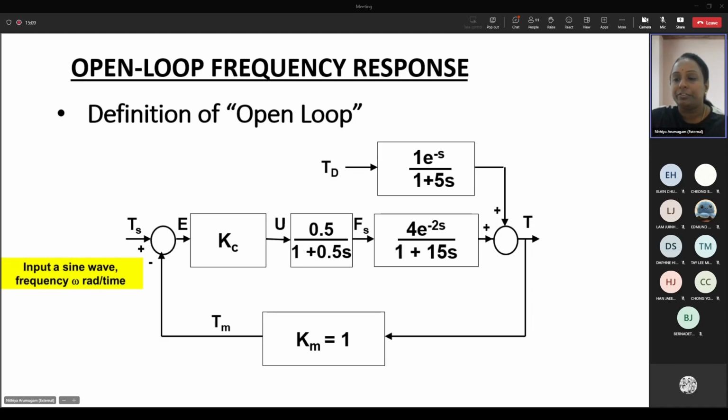So when they say open loop frequency response, it can be used to predict the behavior of a closed loop system, basically. So from here, we can conclude what the closed loop system is, or the stability of the closed loop system. The frequency response method may be less spontaneous than other methods. Even then, it has certain advantages, like in real life situations in which we can use it for modeling transfer functions from normal physical data or experimental data. Okay.